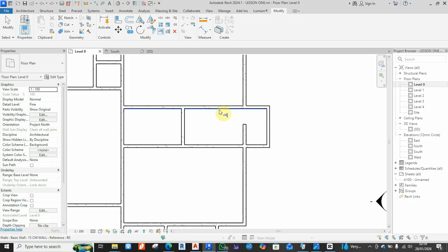I'll click on the wall that I want it to be extended to, like this one. So I want the object to be extended to that line. Then I'll bring my mouse to the element that I want to extend like this, and you can see a green line appears in front, meaning that if I click, the element is extended to this line. So I'll click on undo.